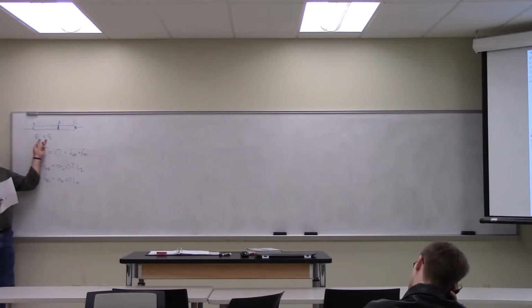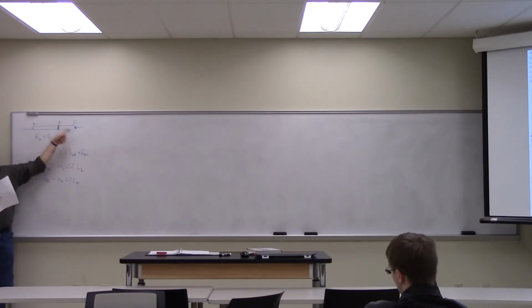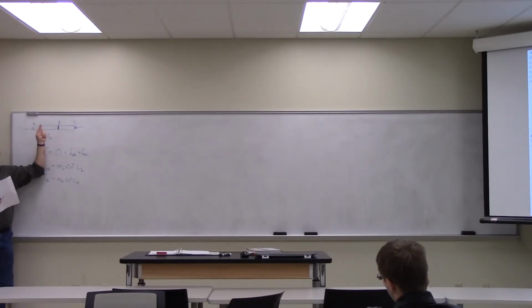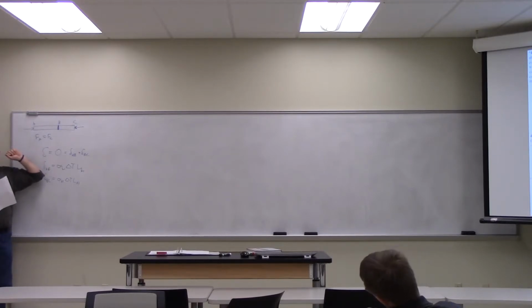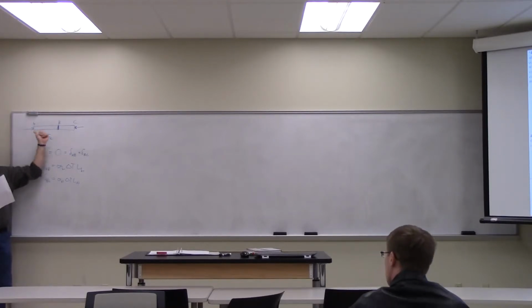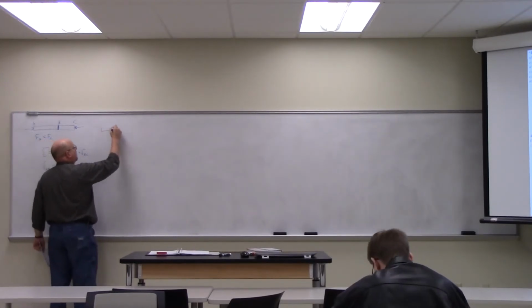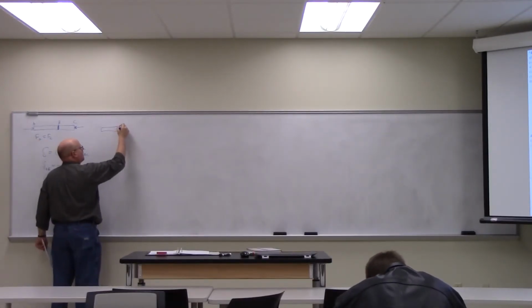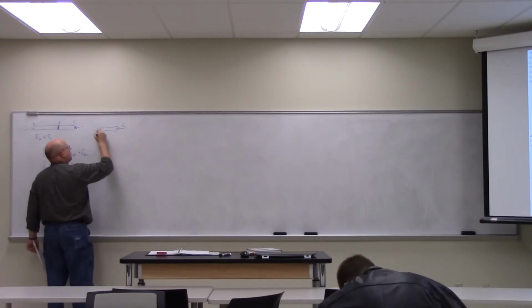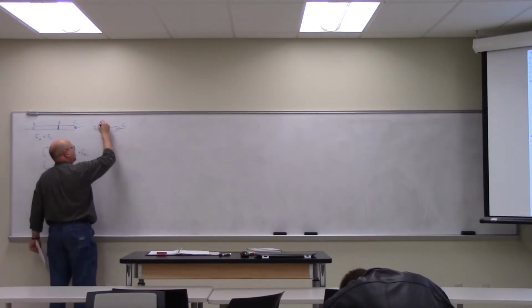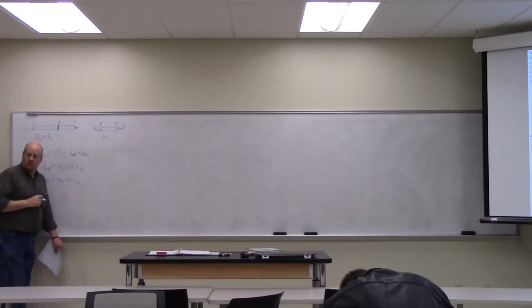Right, so there's still a force acting on this, right? We already said that there's going to have to be some kind of force. This thing wants to expand against fixed constraints. There's going to be a reaction force. That reaction force will also cause a displacement, right? If I just had the reaction force, it would cause a displacement in each of these pieces. So if I just took BC, here's my BC, there's F sub C, this is my internal force, also equal to F sub C, so this is BC. So there's going to be a delta associated with that force.